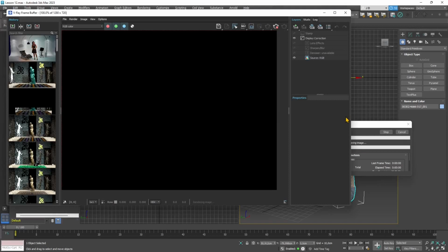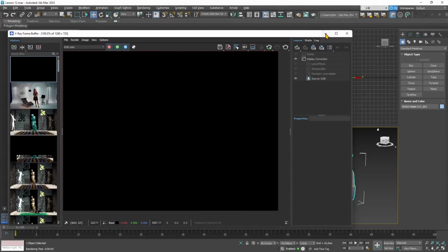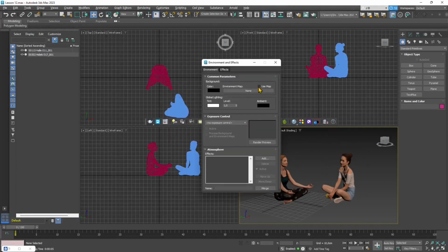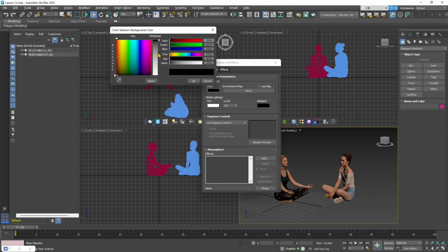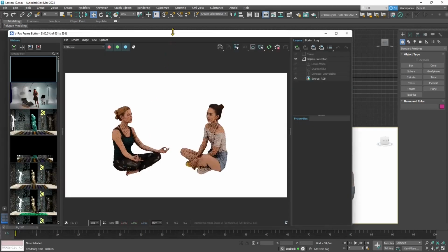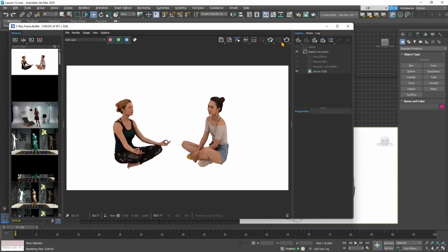And as usual, we're gonna start from zero and then we're gonna build up our scene little by little, and we're gonna run the tests here that are gonna show us our progress in the history panel in the VRAY frame buffer. So I'm gonna run a first render, and as usual, everything is totally black. So this is the first thing we get when we run the first render, and then we're gonna activate already the environment. So the first technique here that we're gonna see, called HDRI and IBL, to render a single object is based mainly on the environment texture or environment map.